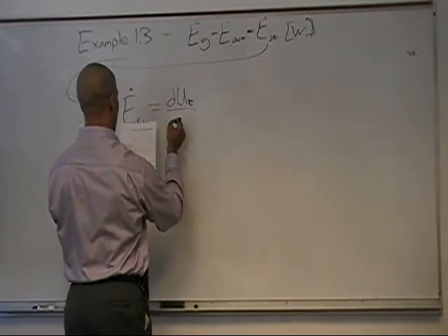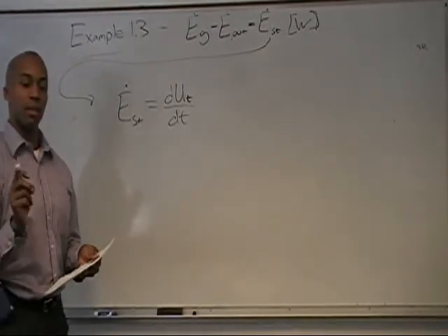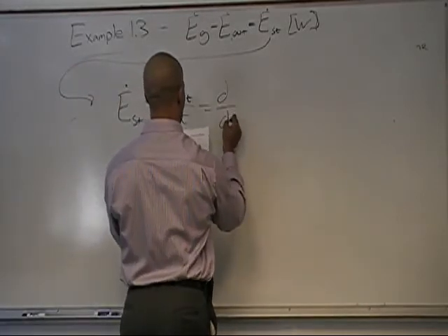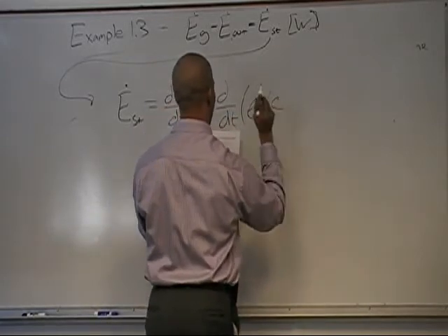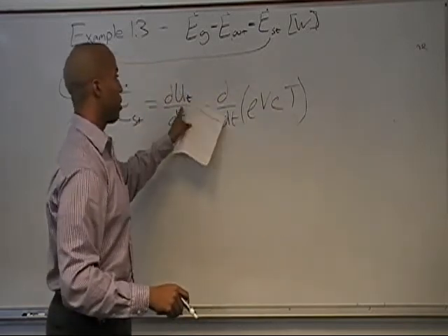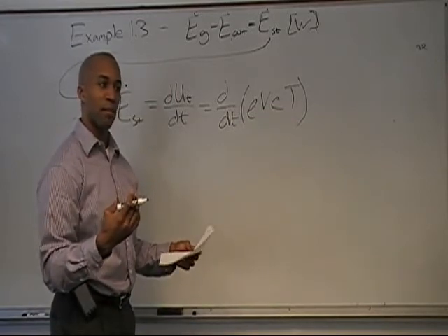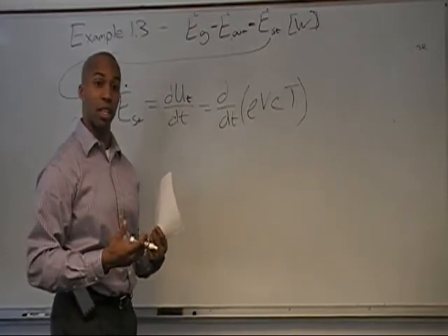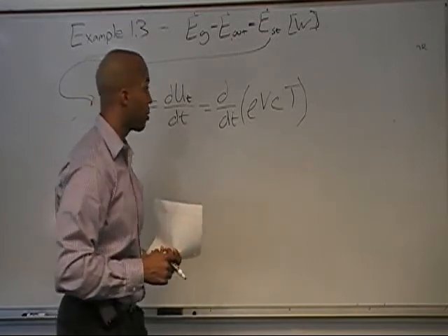And the energy stored is the rate of change of that internal energy with time, which also equals the rate of change with time of the density times the volume times the specific heat times the temperature. Temperature and internal energy are related. Basically, things that have a higher temperature have more internal energy. They have molecules that are moving with more kinetic energy.